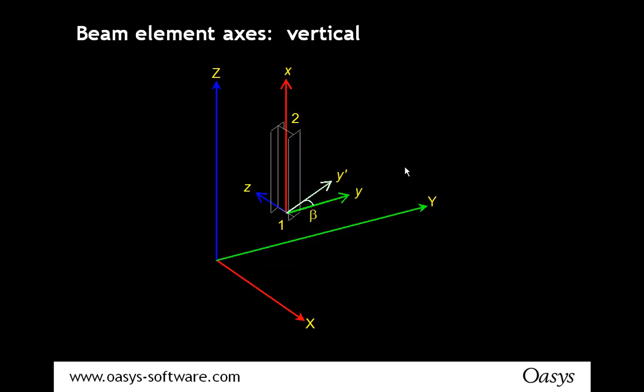You will find though, if you import a column, for example, from CAD, and maybe there are a few rounding errors or it was badly drawn in the first place, you might find the solid section rotating round as you view it, and that's because the column is not quite vertical. Something to watch out for.